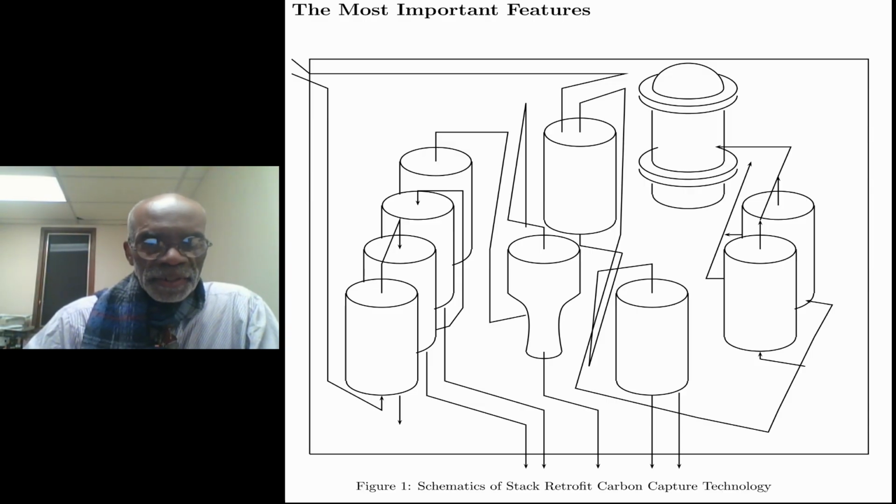In the scrubber, distilled water is first aerosol mix sprayed into the gas, and then subsequently higher jet spray into the gas to cause droplet coalescence, as well as drive the droplets to the walls, where the droplets impact the wall and then roll down the wall.